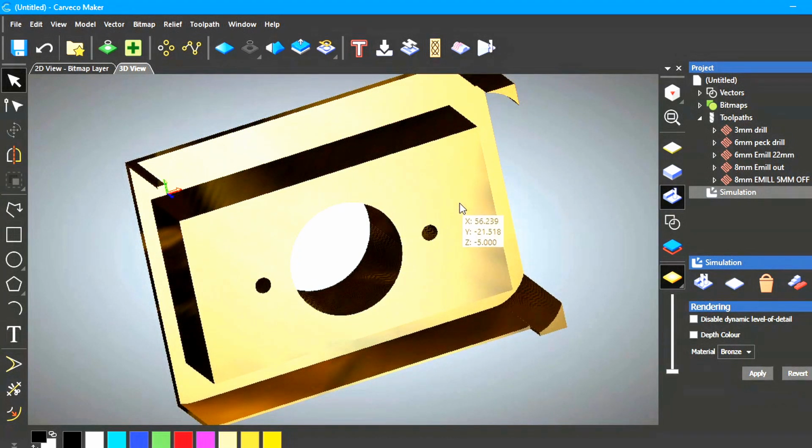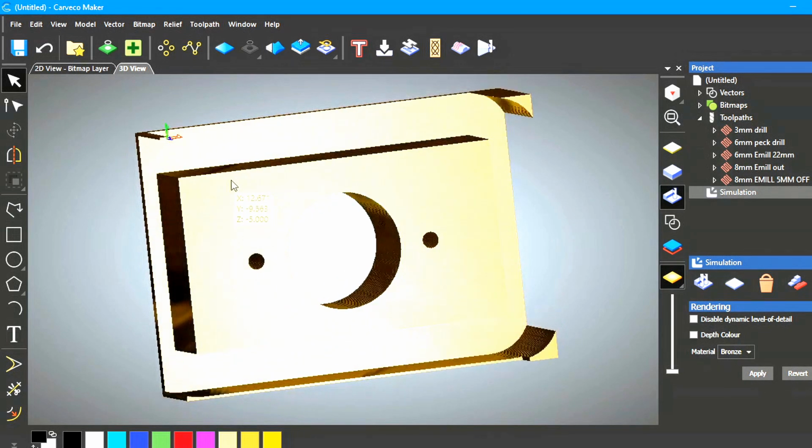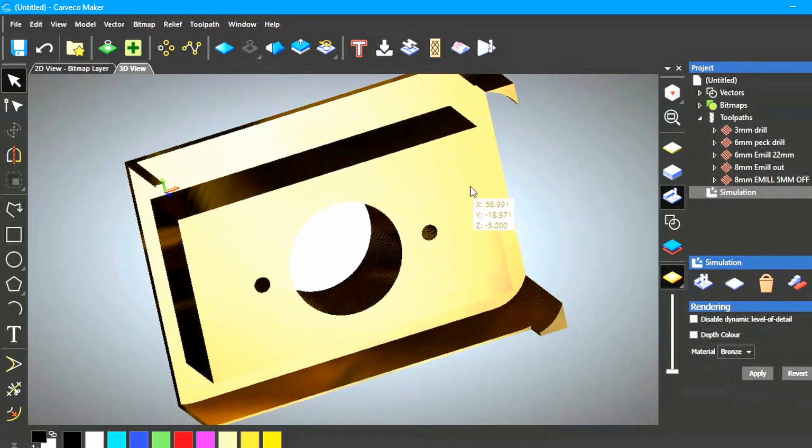Okay, so the next thing to do, and the last thing, look, I do have to bore 2 holes in here, and I'm not sure of the dimension I want yet until I get this mounted on the ball screw and have my plate manufactured. I'm not sure where I want these drill holes. So for now, this part is going to be finished. I'm going to be making 4 of these because I've got 2 ball screws on the y-axis and of course the x and then the z.